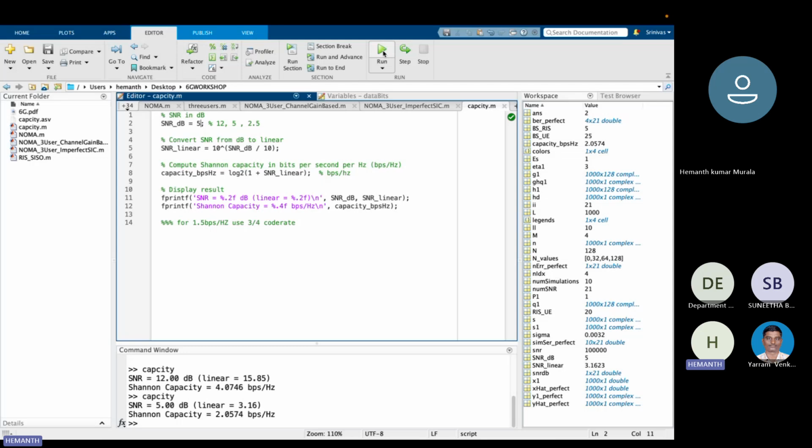Okay, in digital communication, 5G technology. Clear? So what is this idea? Concept is understood. In 5G, whatever mobiles there are, all mobiles work on the basis of your signal to noise ratio. So in the morning session, sir asked the question: why are we not getting the proper signal? Voice call is not proper, data is not proper, because you are not receiving the proper SNR. If you receive the SNR at least 5 dB, then QPSK modulation works. More than that, you can go for 16-QAM. Like this, up to 256-QAM will be supported in 5G.